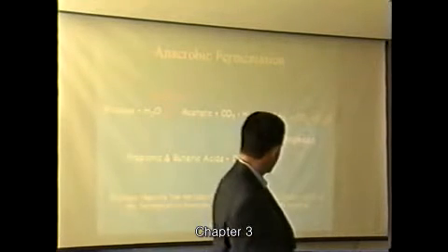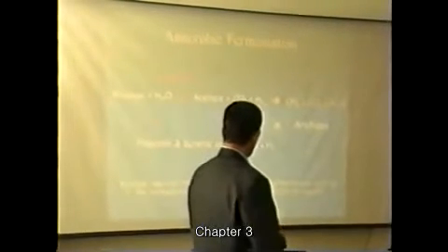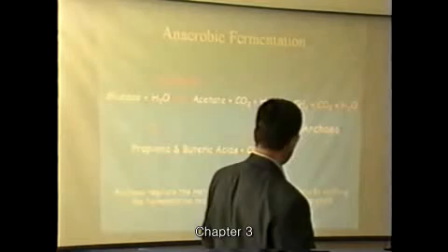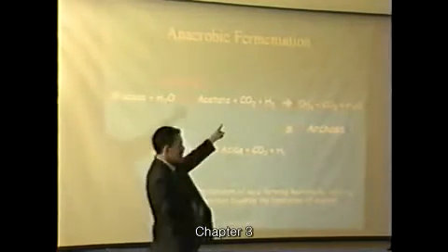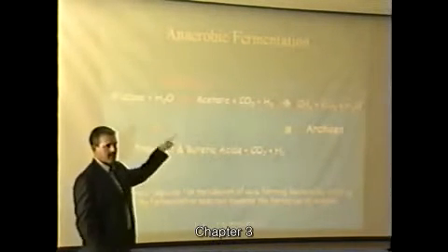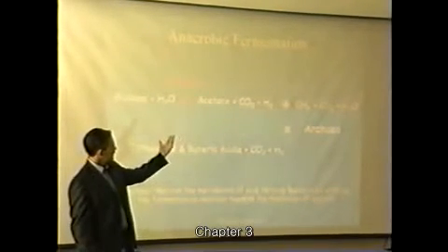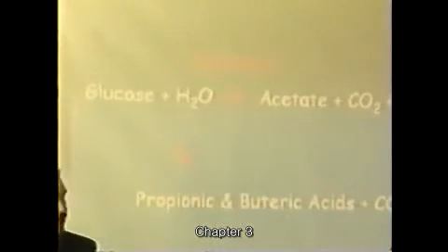So what archaea do is regulate the mechanism of acid-forming bacteria by shifting the fermentation reaction towards the formation of acetate. What I basically mean is the faster you can remove your hydrogen, the faster that reaction will move to the right. If you have a restriction on your hydrogen removal, you have a problem.